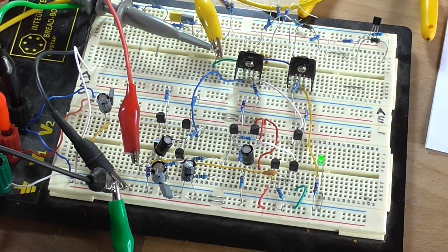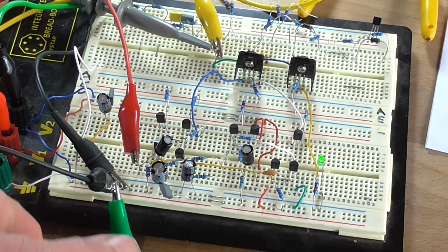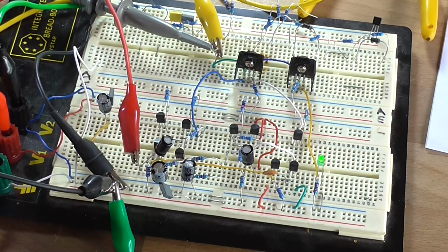Could this circuit be improved? Yes, most definitely. But for the average output power we're getting, which is around about the 85 milliwatt range into average loads, it's not bad. It can certainly amplify from a line signal with a volume potentiometer in between just fine. So yeah, you can amplify a CD player, tape deck, computer, whatever.